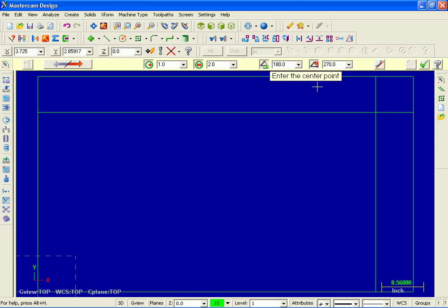Now enter the center point. I'm going to move on and select this intersection point. And there's our arc. I'm now going to select the apply button. Now for our next arc, I'm going to move on up, click in the radius section, type in 1.0, hit tab, over to diameter, hit tab again and start angle. I'm going to input 270, hit tab, and for the end angle 0, I'm just going to leave it and hit enter.